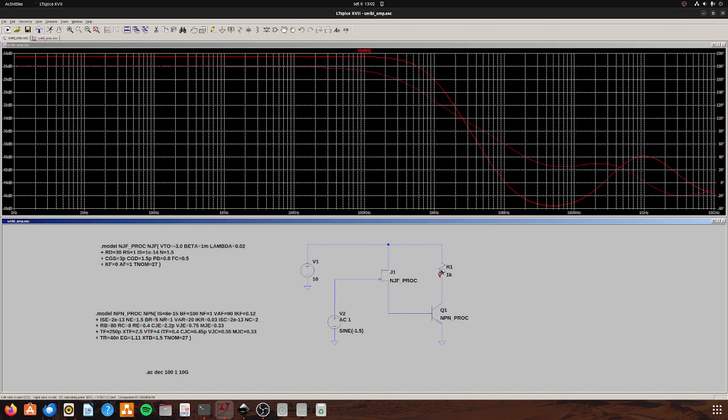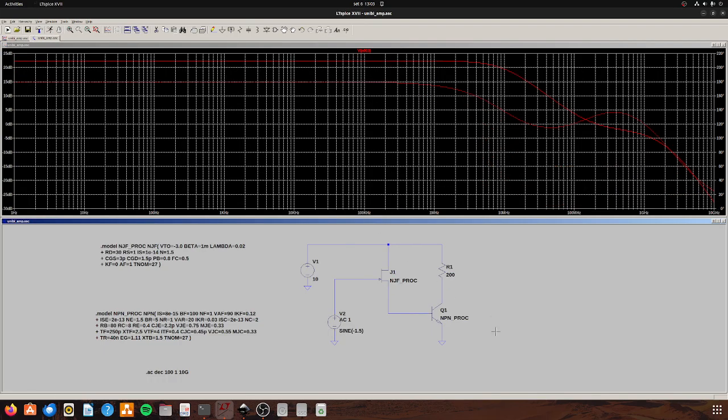Oh, it didn't actually increase because the DC point changed a lot. So we need to basically see a simulation in order to see where the DC point was. But if I do this, it probably increases. Yes, because it doesn't change the DC point too much.